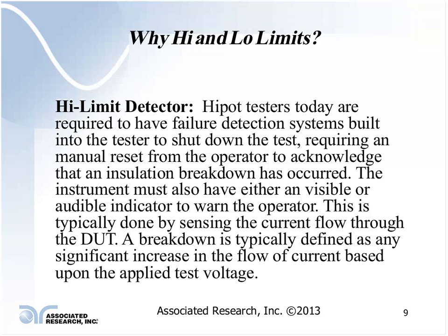The operator doing the continuity test became the return path because she was standing on a concrete floor, or actually leaning up against the conveyor that the product pallet was actually setting on. So the product was sitting there isolated and energized at 1240 volts.